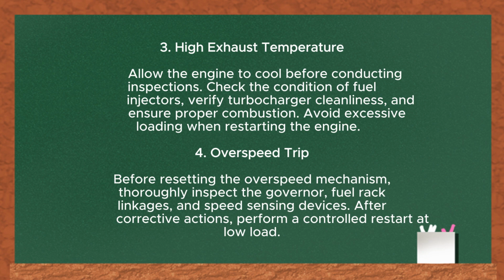And the 4th, overspeed trip. Before resetting the overspeed mechanism, thoroughly inspect the governor, fuel rack linkages, and speed sensing devices. After corrective actions, perform a controlled restart at low load.